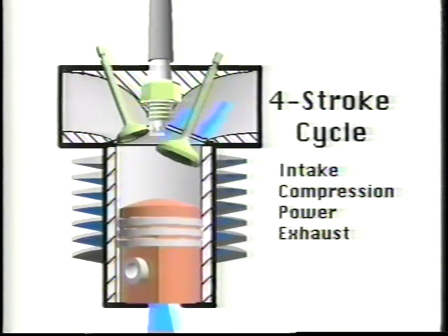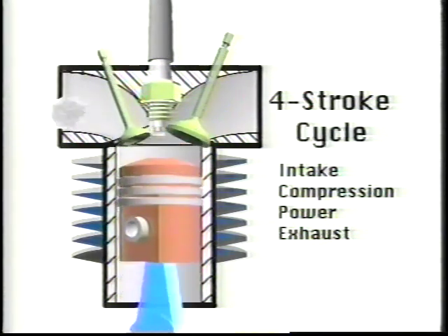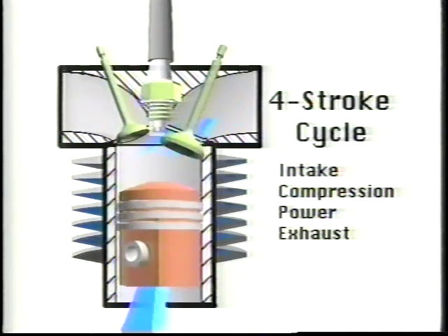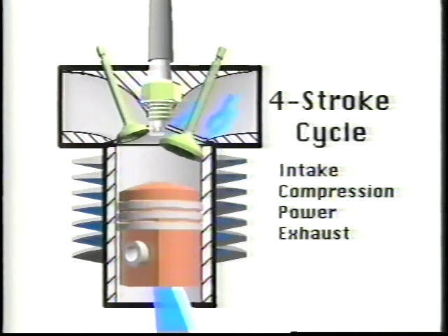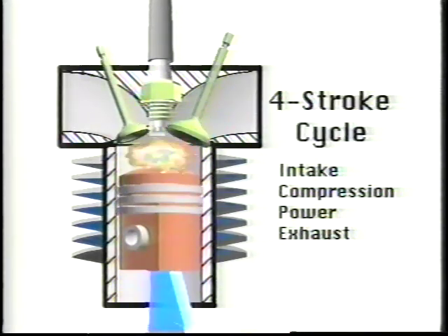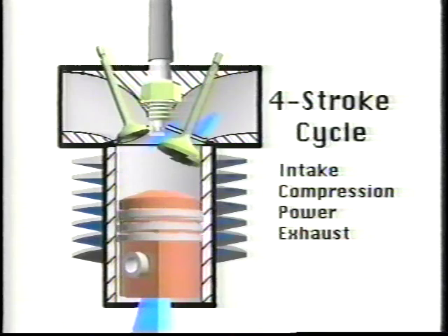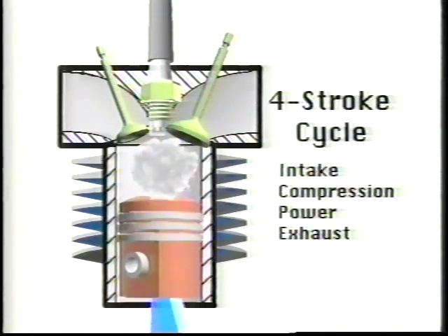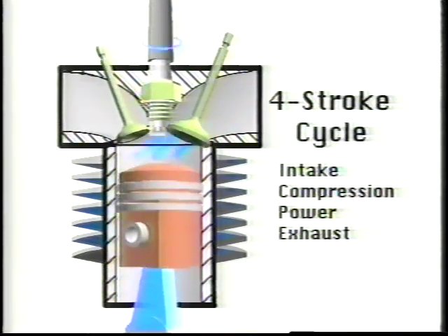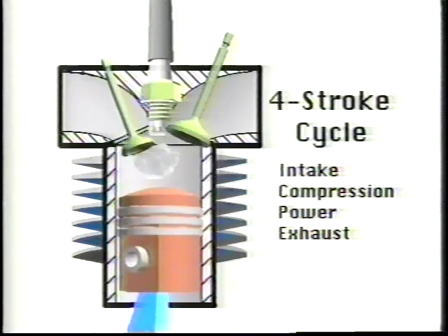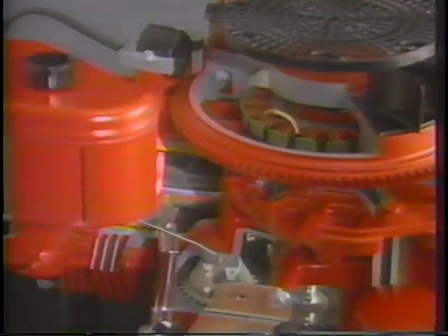During actual engine operation, these 4 strokes happen more rapidly. Remember, on the intake stroke, the intake valve opens so that mixture can be pulled into the cylinder. On the compression stroke, both valves are closed and the mixture is compressed to ready it for combustion. On the power stroke, the spark plug fires to make the fuel mixture burn and expand, and on the exhaust stroke, the piston slides up and the exhaust valve is opened to purge the burned gases from the engine. Discussed later, a 4-stroke cycle engine also has many other components to support its operation.